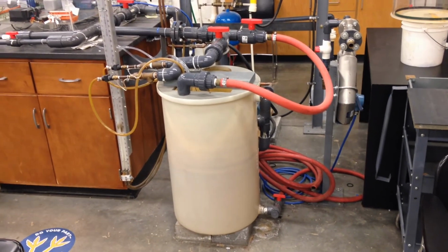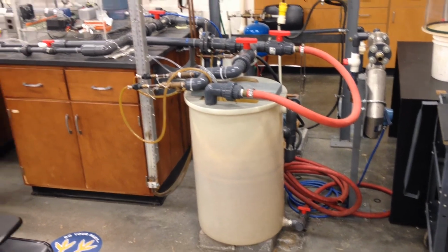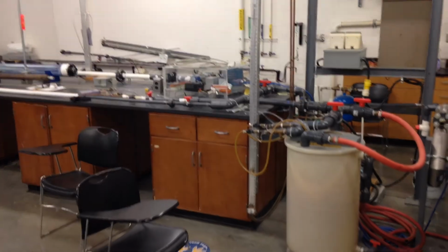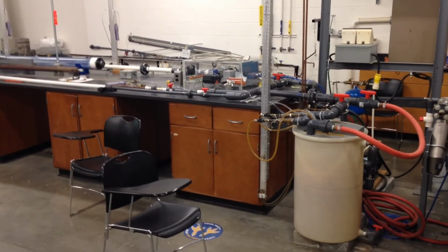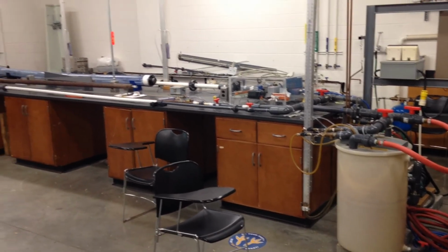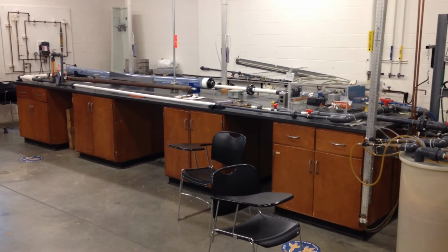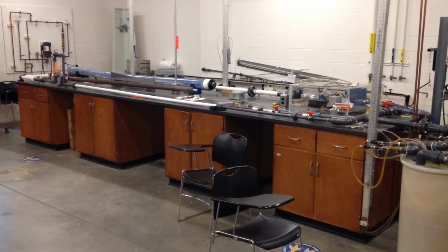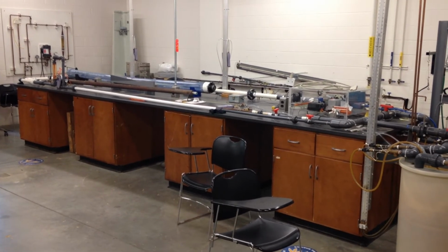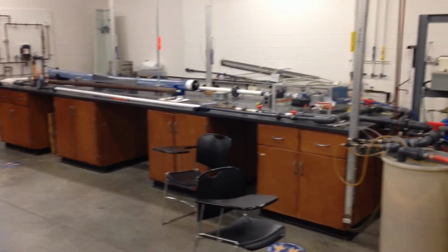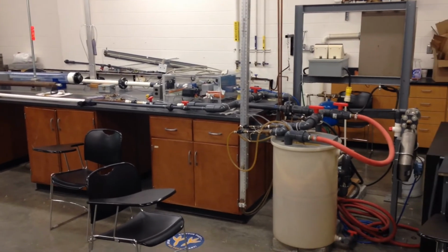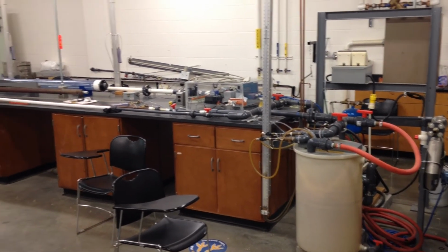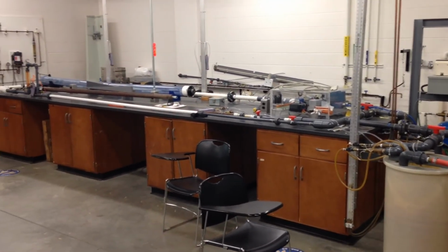The experiment itself will be divided into 2 different parts. The first part will be, we're going to look at the conventional flow meters on the far side of the table, and the rotometer and the minor loss over here on the near side of the table. And that includes, of course, the second orifice right in front of you. The second part of the experiment will be the Moody chart through that copper tubing.